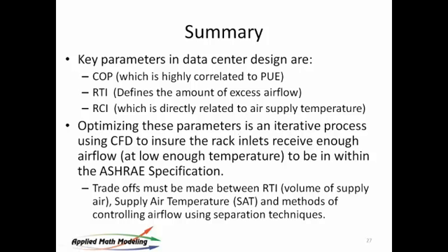I wanted to do a quick overview of some of these key parameters, how to get your hands around them. We reviewed coefficient of performance, which is very highly correlated to PUE. It is really the dominant characteristic of PUE. And again, it is simply understanding how much energy is going to your cooling system compared to the IT load in the room. Those are the two things you want to measure. Those are the two dominant energy components in your room, the cooling and the IT load. Make a ratio of those two things. Find out how to measure it.